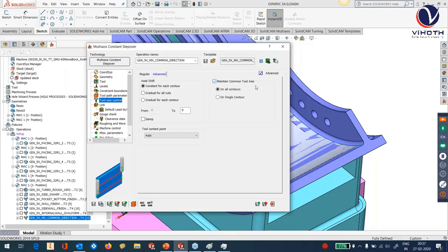What this is basically going to do is try to find the best possible approach to the surface in such a way that it can lock the 4th and 5th axis at particular angles and machine the entire surface in pure 3-axis. Although we have set 5-axis, the result is actually going to be a 3+2 result. And these exact angles are going to be found automatically by SolidCAM. Okay, it's amazing. It's an underdog again. Let's calculate.